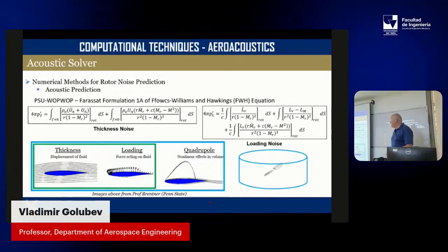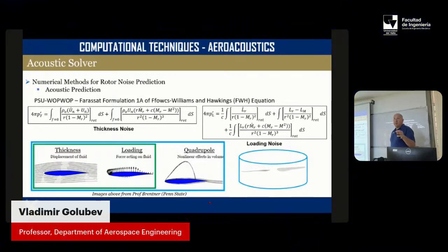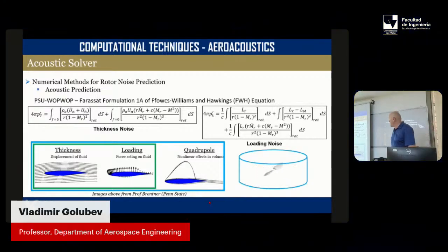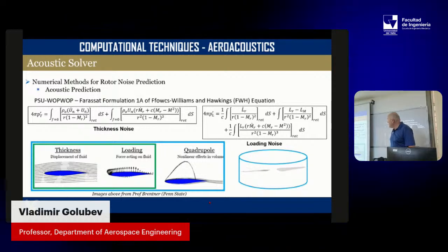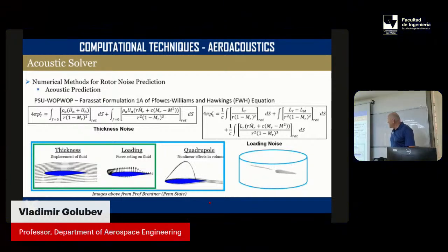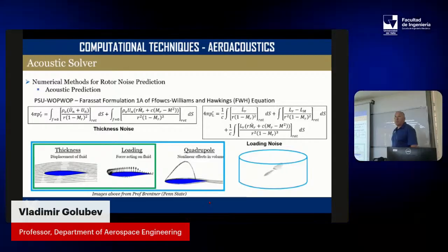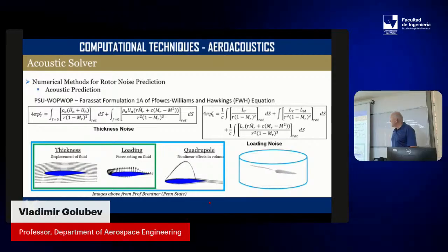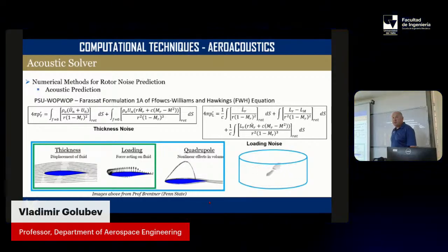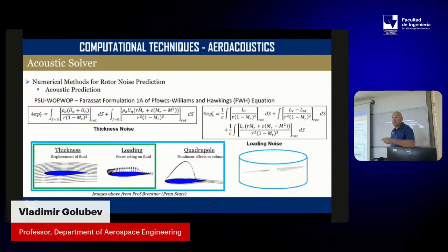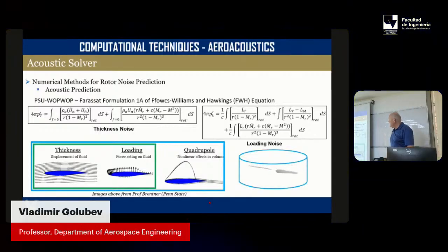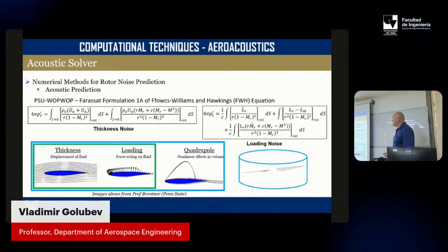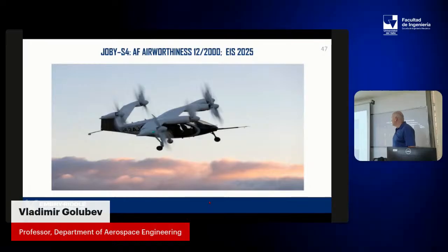The one which is developed by the loading is called dipole source, by thickness displacement it's monopole, and by the turbulence and all kinds of things, it's quadrupole. And so this is usually the control surface, which would coincide with the surface of the blade. It's called an impermeable surface. Or if you have the control surface outside and you just get your CFD results on the control surface and propagate far away using the formulation, this is called permeable surface. That's just some terminology, but that's it.